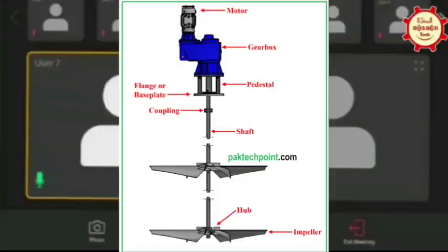I think Anshul, you want to add something, because you answered something in the group. Actually, whatever thermal expansion you get after the calculation will be fixed. Other than that, the agitator movement you are talking about would be mechanical pull. You have to check with your agitator supplier how much stretch or elongation would be there because of the mechanical force, because thermal will be fixed.